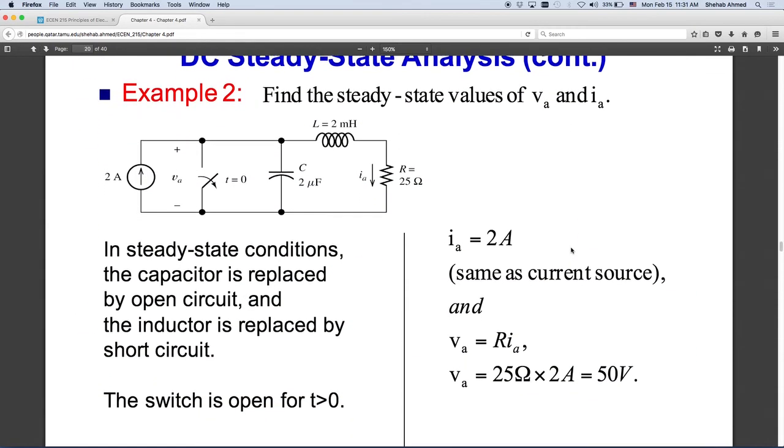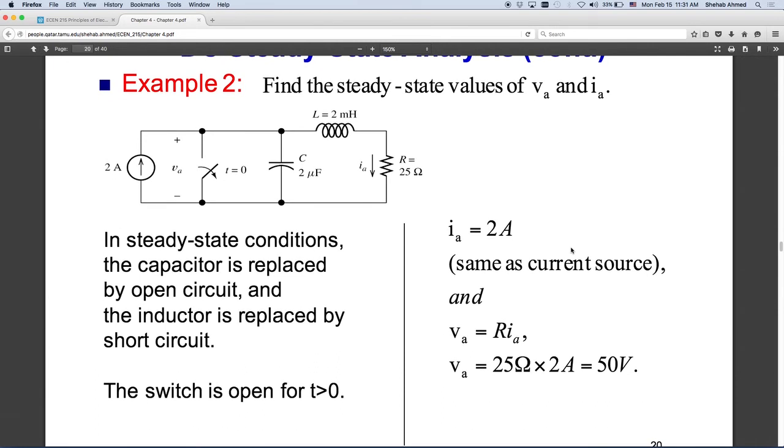Same thing with this circuit. You have a current source here, and I'm turning open the circuit. The switch is being opened at t equals 0. Right? So before t equals 0, it was closed. What was happening? The current flowing from this source was flowing in this short circuit. And now after I opened it, what's happening? Current flowing from this source will go into my RLC circuit combination. If I'm worried about the transient response, then this is a second order differential equation, a second order system.